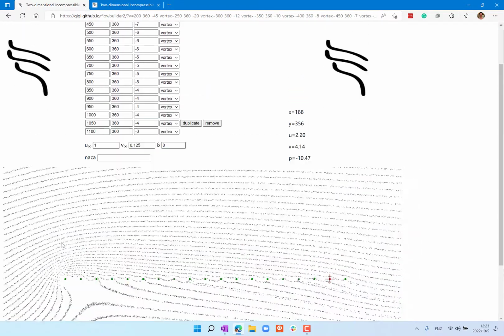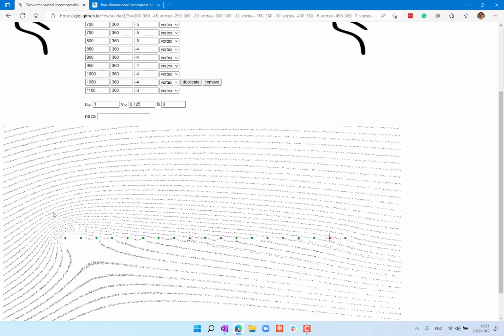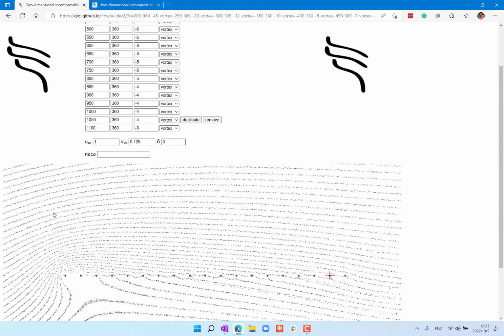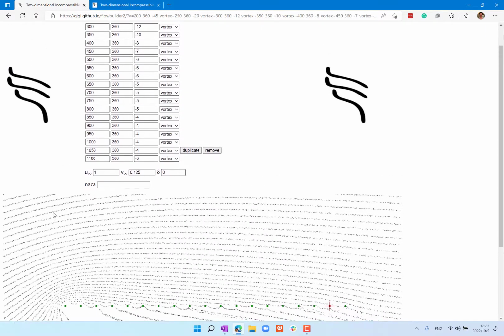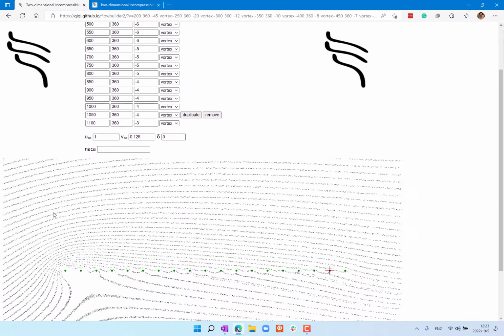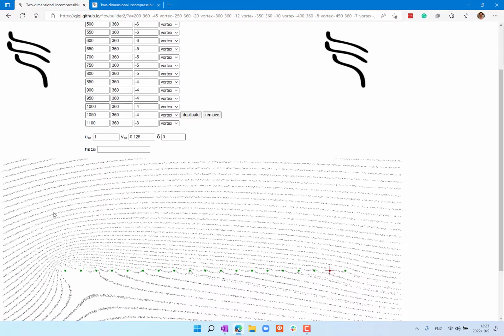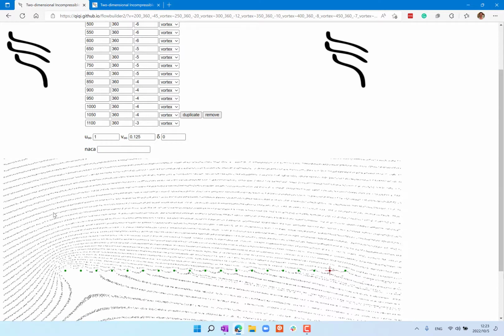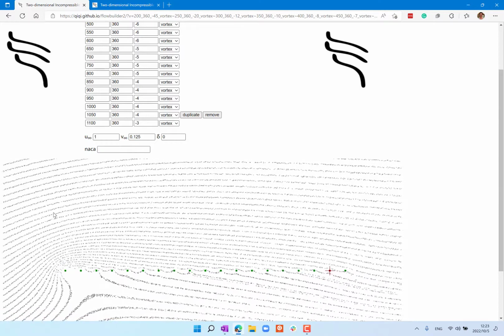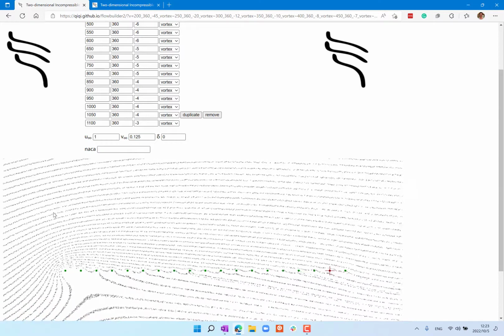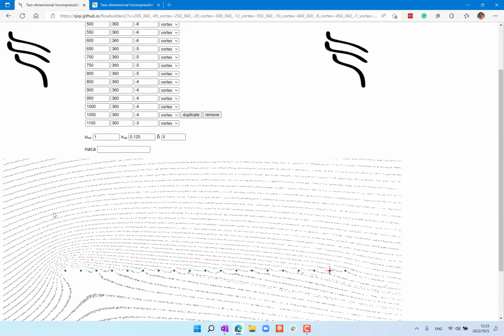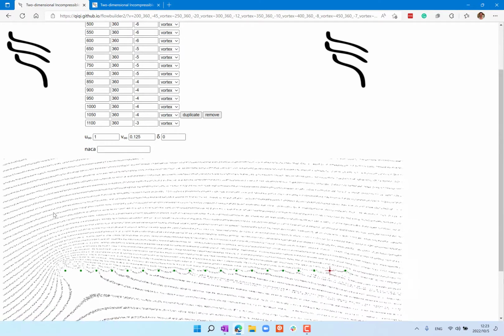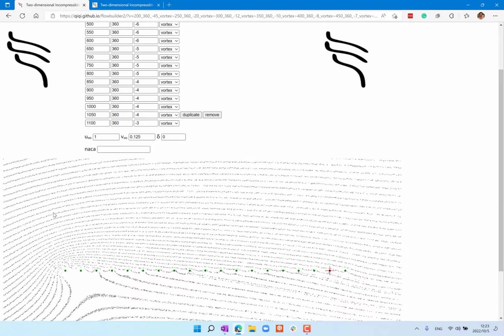And if I have a strength of 20 here, then I have a lift force proportional to 20 over here, and then a lift force proportional to like 12 and 8 and 6, etc. So basically I have a high lift over here, less lift over here. If you think about the total effect and balance the total lift at some point, where do you think that point is, roughly?